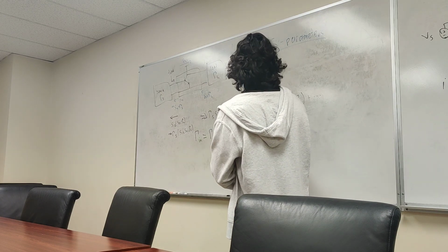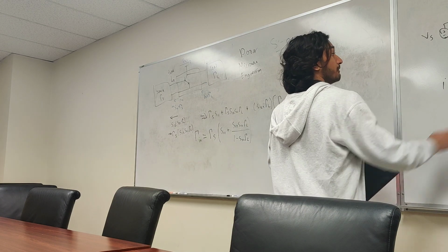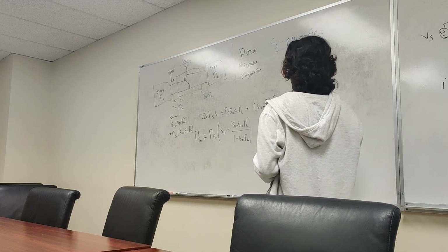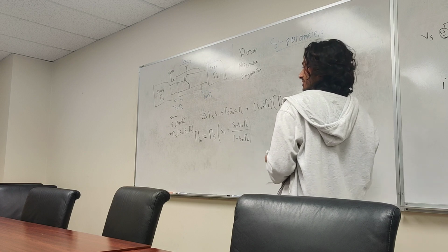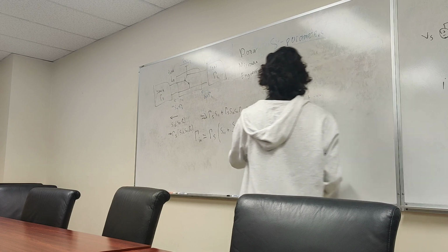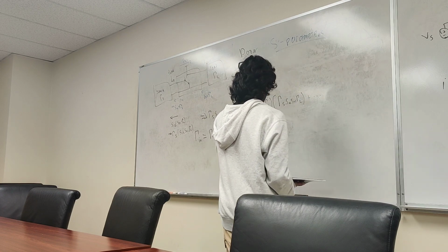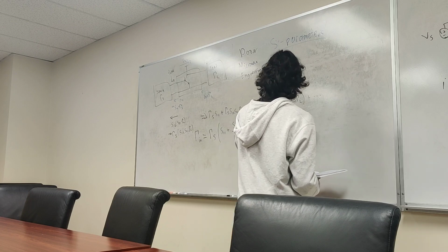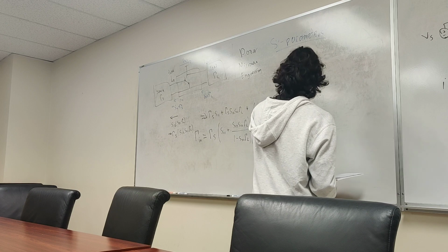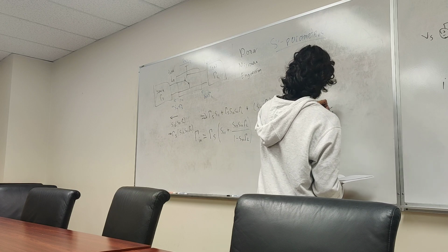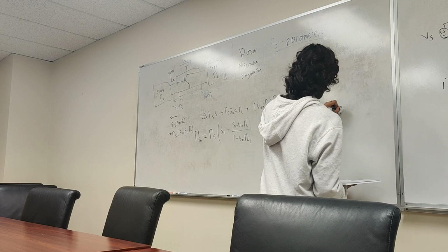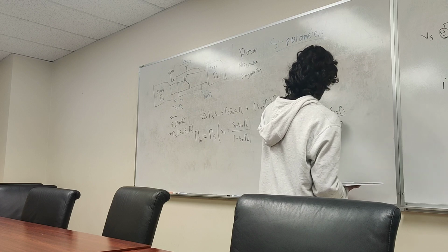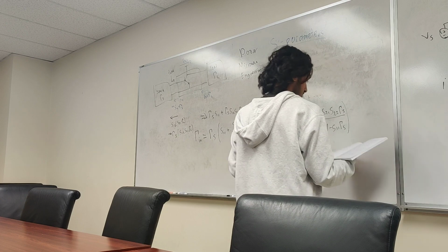Okay, so this is your gamma in. It's what we wanted to find here, right? So we found gamma in. Can we find gamma out? Well, if you want, we can redo this whole thing, or by symmetry, gamma out is going to be equal to S22 plus S21 S12 gamma S over 1 minus S11 gamma S. Cool.